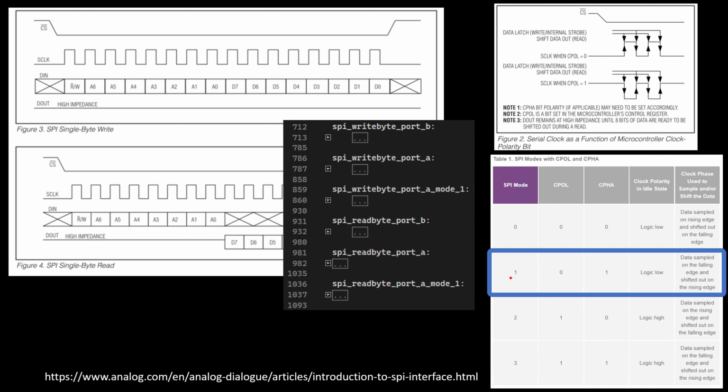Those are pretty similar to their previous counterparts, but they simply flip the clocks around compared to when I'm going to have MOSI ready. So just make sure that MOSI is correct when the clock falls, so that this SPI mode 1 is compliant in what I'm sending out of it. That got me the basics of how I'm going to send data.